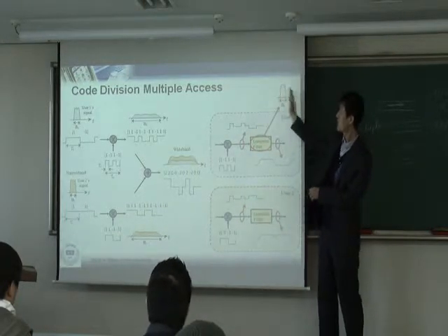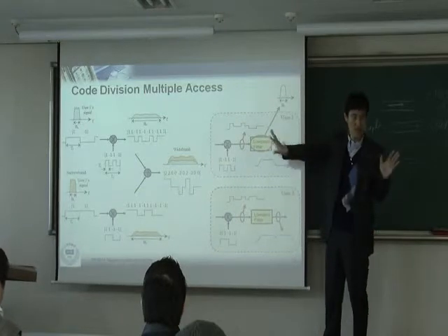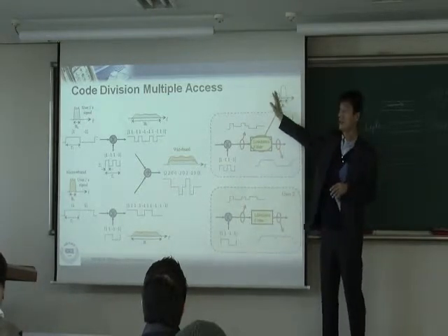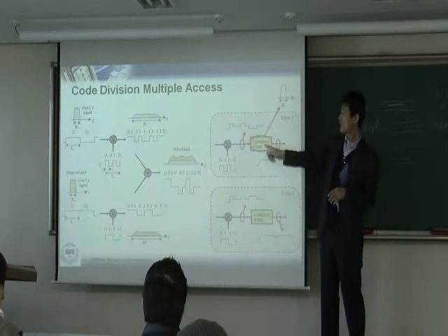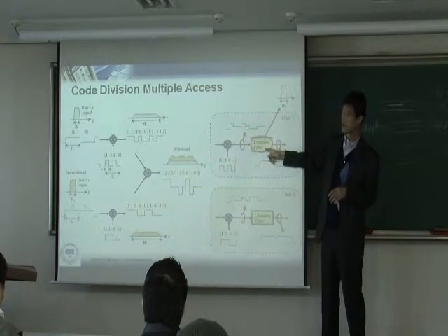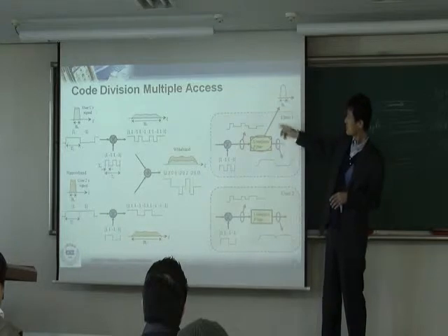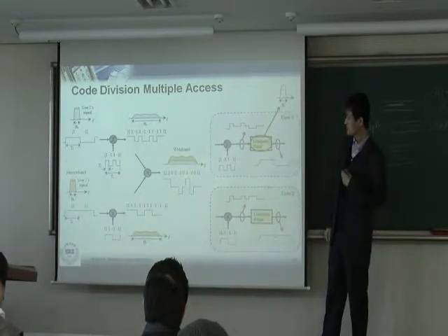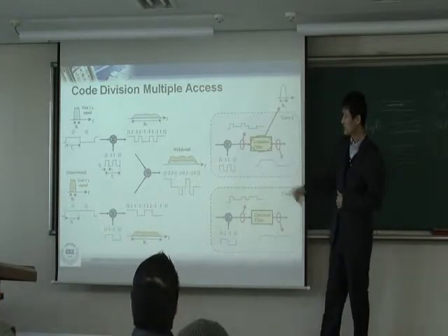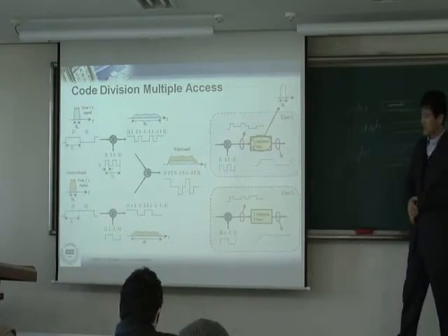That way you remove all the out of band spectrum. You want to clean the spectrum, therefore you apply the low pass filter. So you want to get this original narrow band signal. From the time domain perspective, this is what you receive. So that's a basic concept.